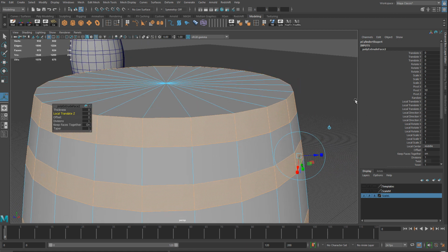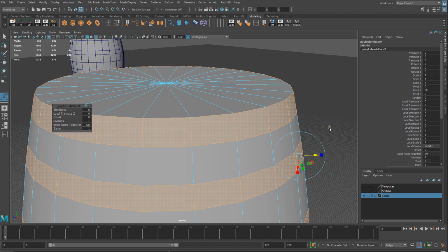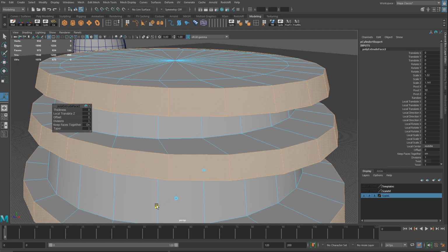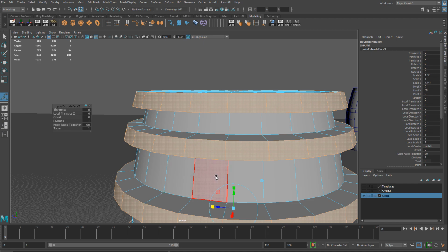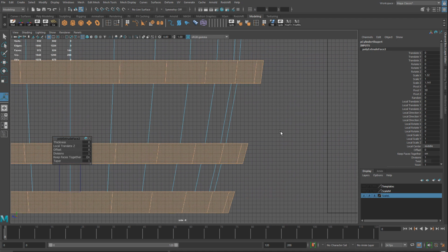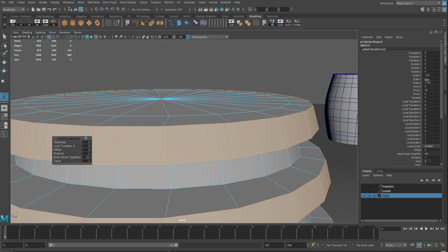So for the scale, I could drag these, but again, I could change my transformation from object to world, and this will actually scale them straight, like so, and there won't be any angle to it. And after you scaled, you can see that my scale X and scale Z have been modified. So those are the two translate versions, orientation axes that I can now modify more precisely.